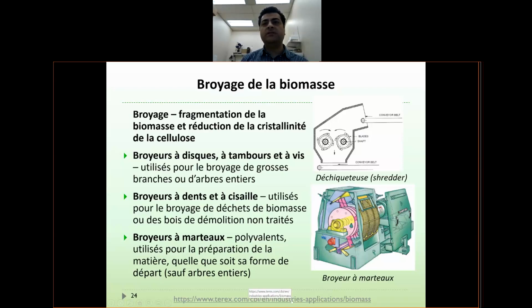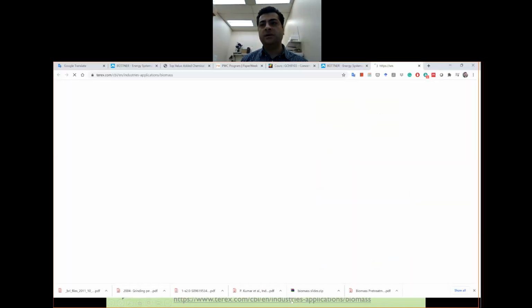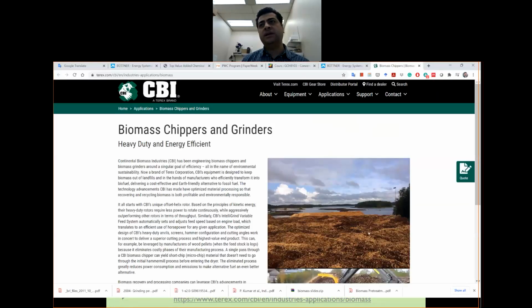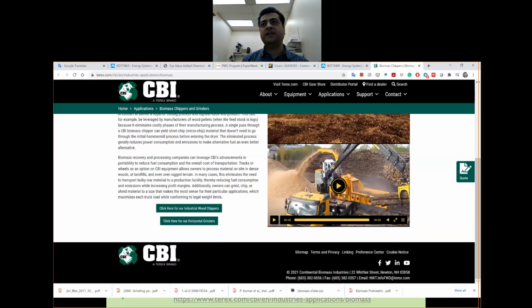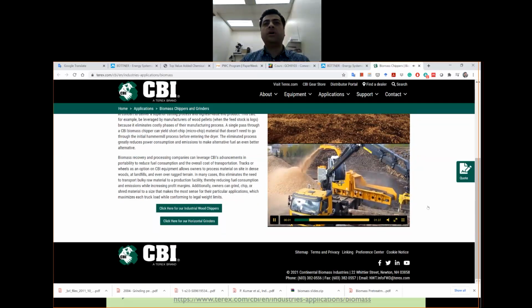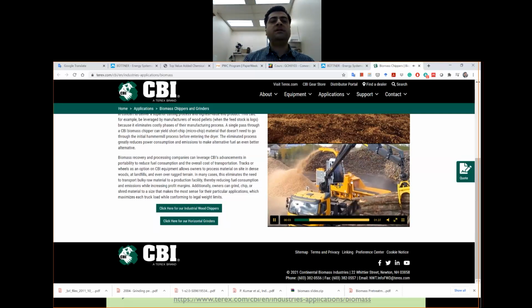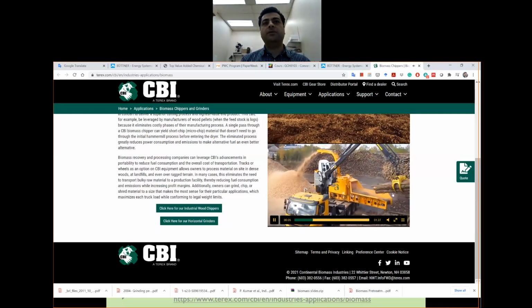Therefore, at the exit of the dryer, usually we need to have an air and solid cyclone. And also at the end, here is the stack, but before the stack there should be a special unit, for example, an absorption column, something in order to absorb or condense those evaporated volatiles from biomass.